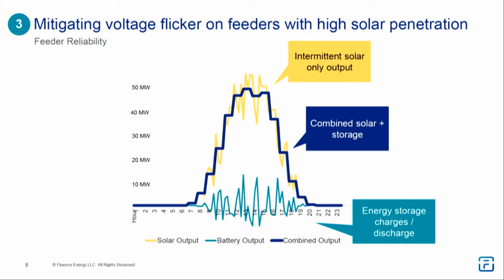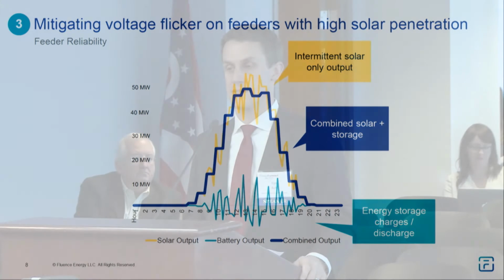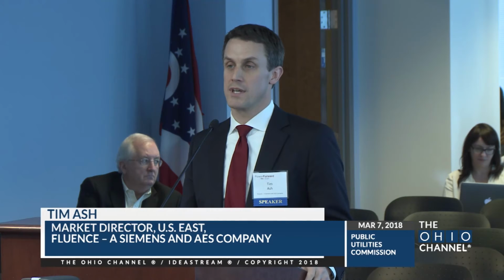In addition, if you have a lot of solar, for example, in a distribution network midday, low load, you get reverse power flows and again some voltage stability issues potentially. So deploy energy storage, it creates that shock absorber effect, absorbs energy to put back in as it's needed and address some of those issues. Again, you can help improve the reliability, potentially lower cost. You reduce wear and tear on the equipment, you avoid the need for investment in other infrastructure.